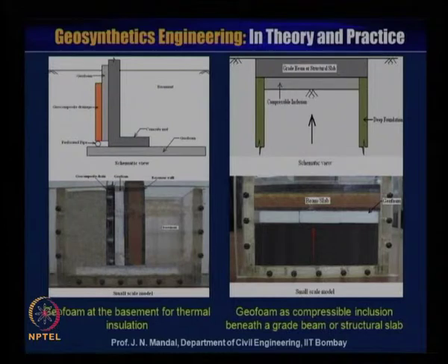So geofoam here as a compressible inclusion beneath a grade beam or structural slab. So this is the structural slab, this is the deep foundation, and these are the grade beams down. On the base of this beam you can provide the geofoam. Here you can see this is the geofoam and this is the beam or the slab.